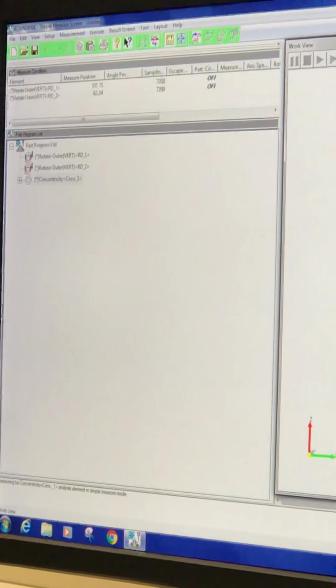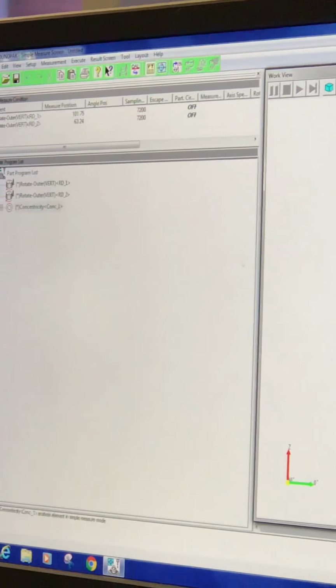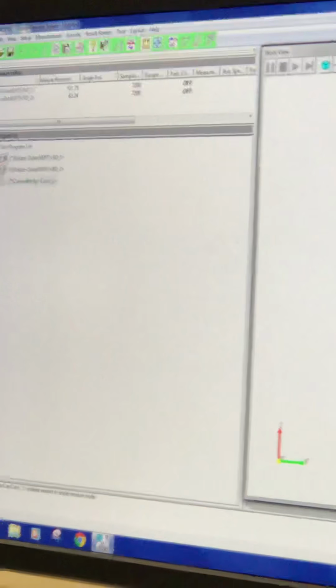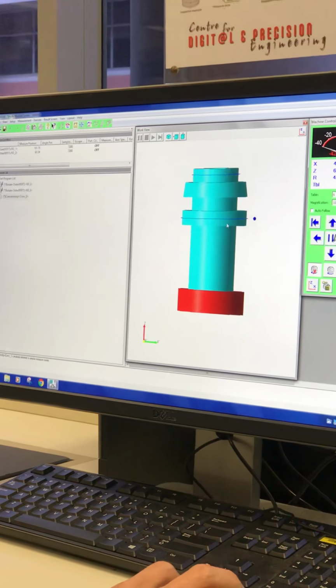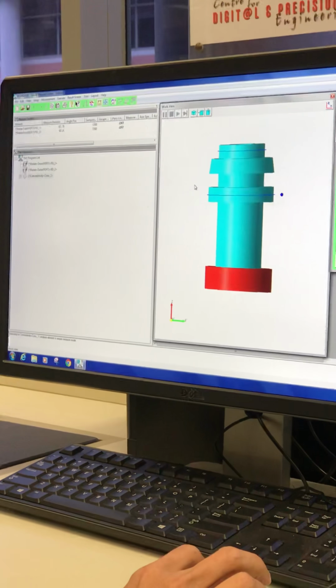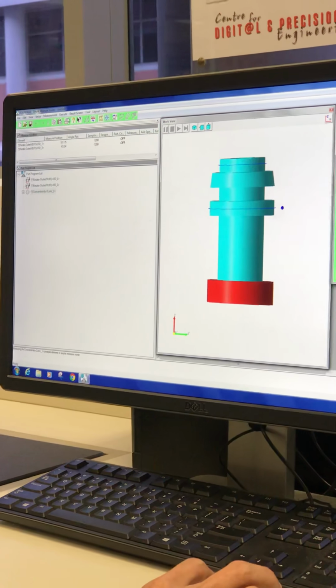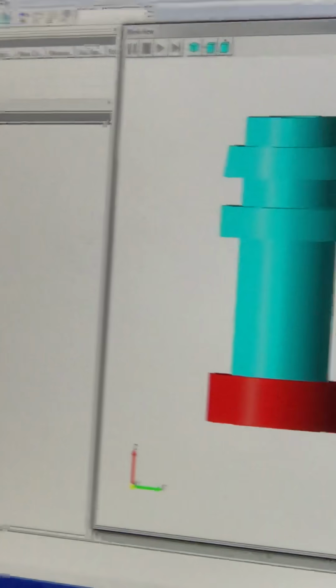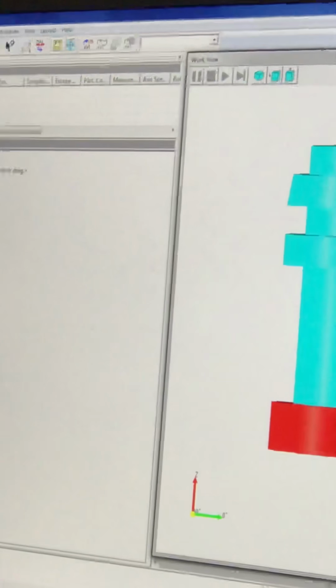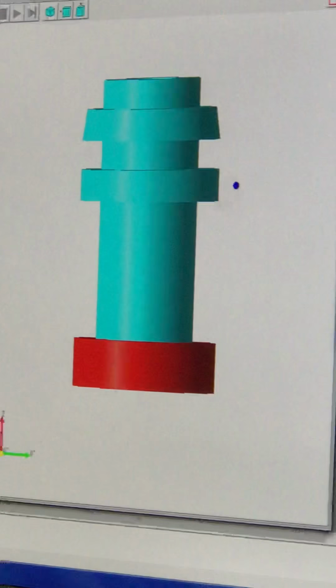You can now bring the stylus to the top here to measure cylindricity. Any question? Cylindricity, you need to use CNC mode. Okay, so you need to come here. Uncheck simple measurement, change to CNC mode, or programming mode. Uncheck this, then the screen will change to gray. Can see gray color. Just now it was green, right? Now change to gray.